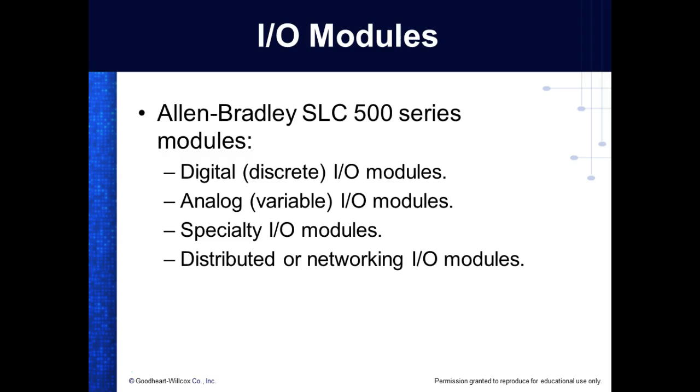It takes 5 weeks. So we got bits, we got nibbles, we got bytes, we got words, we got double words or long words, we got double long words. So 16, and then 8 is a byte, and 4 is a nibble. So with Allen Bradley, when we have a 16-bit input module, that would take 1 word of memory. And every bit inside that address would represent what goes on with that module. We can actually see this, guys. We'll show you some stuff.